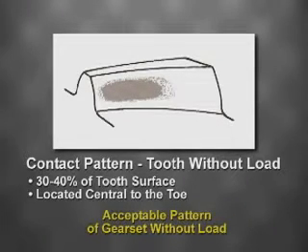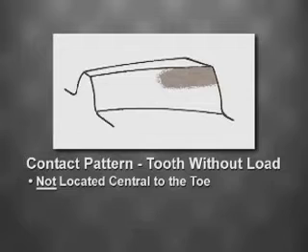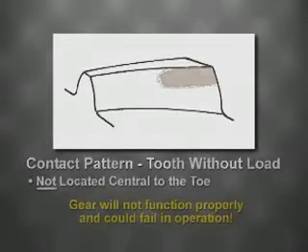But what if the pattern is not correct? Here is an example of a pattern without load that is not located central to the toe. With this pattern, the gear will most likely not function properly and it could fail in operation.